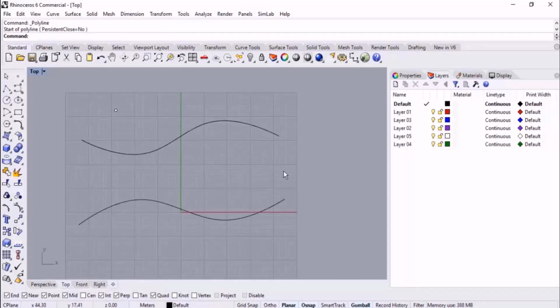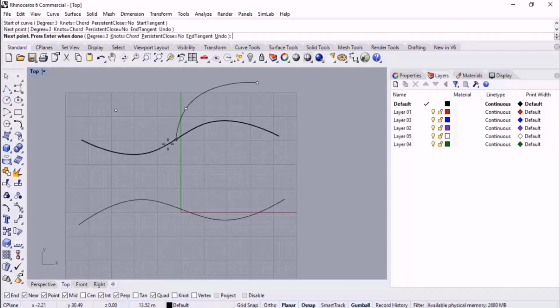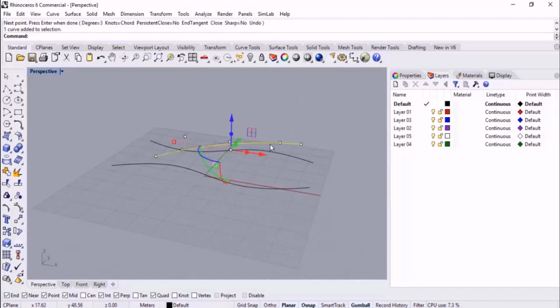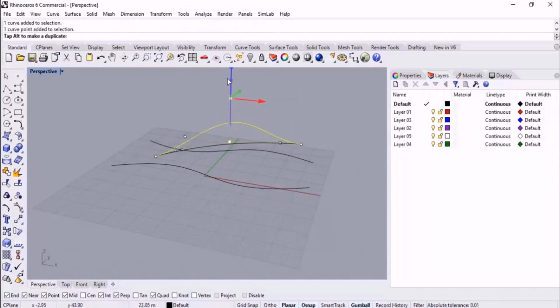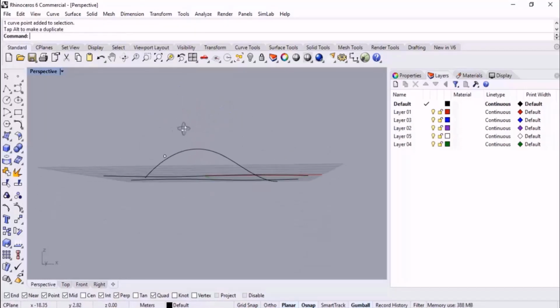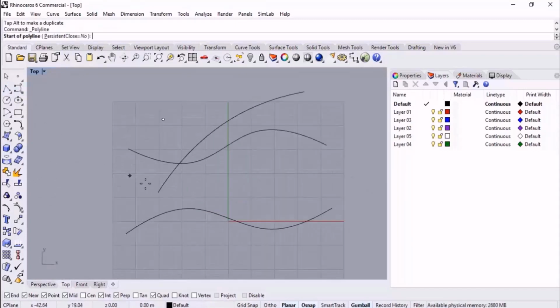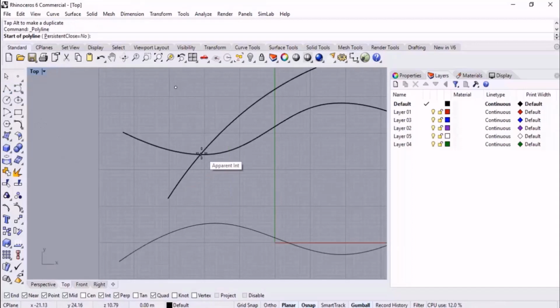If you remember, I told you a point about the intersection, but I'm gonna tell it again, don't worry. When we got two lines that are crossing through each other, there we got intersection. But if we didn't have an actual intersection between two lines, still the snap of intersection does work out. As you can see in the top view, these two got intersection.